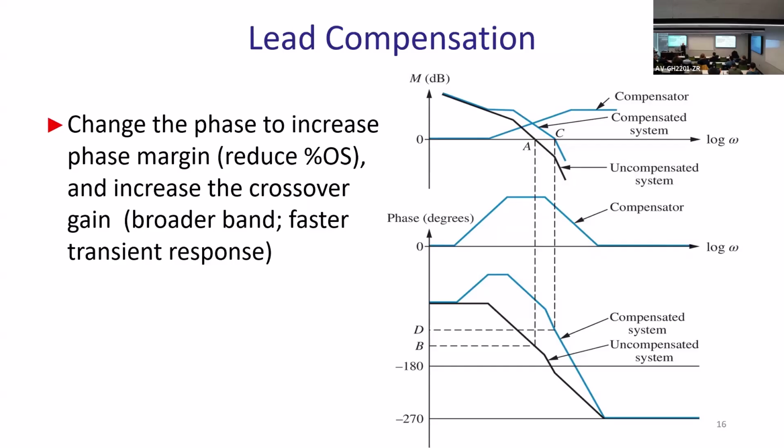So you need to put it not far away to the left. You need to put it exactly at the phase margin where you have it, or very close, okay? Because there you want just to improve the phase without changing gain too much, but gain will change. You cannot do anything about it, because wherever you change phase, gain also will change, all right? And gain will look the other way, not the way you want it to look. It will go from a lower one to a higher one, so it will actually reduce the DC gain or all of the lower frequencies. So you need to compensate for that somehow, which means your original gain needs to be even stronger at DC level, all right? And this is how you design that.